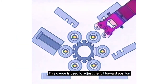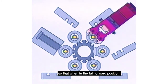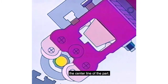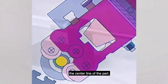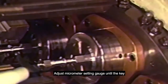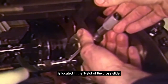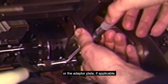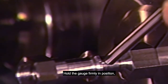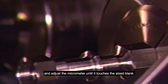This gauge is used to adjust the full forward position of the cross-slide so that when in the full forward position, the thread rolling attachment will be aligned over the center line of the part. Locate your micrometer setting gauge. Adjust the micrometer setting gauge until the key is located in the T-slot of the cross-slide or the adapter plate if applicable. Hold the gauge firmly in position and adjust the micrometer until it touches the sized blank.